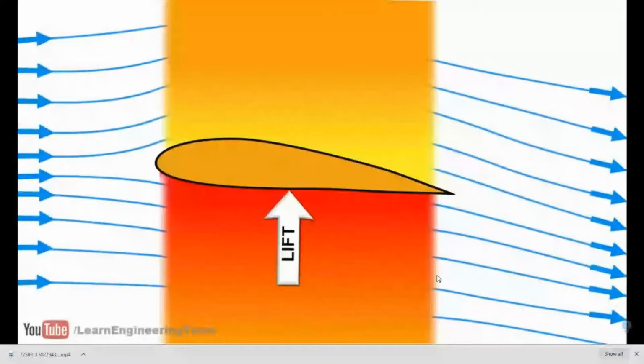But then, why are airplane airfoils not shaped like this? The reason is to give structural support and a space for accommodating the fuel tanks. Is there any fundamental law of physics that justifies the lift rather than this fluid mechanics-based explanation? Yes, Newton's third law of motion. You can see that the airfoil deflects the flow as shown, or it pushes the flow downward. So, according to Newton's third law, the air also should push the airfoil in the opposite direction with equal magnitude.